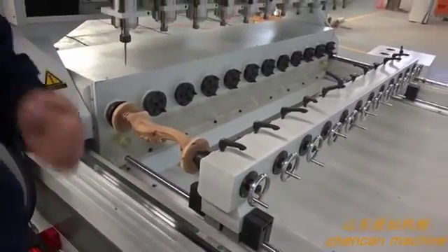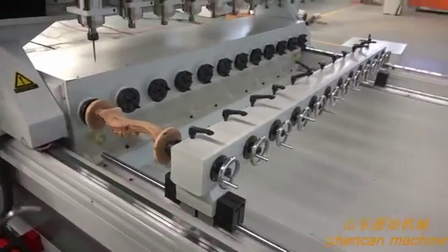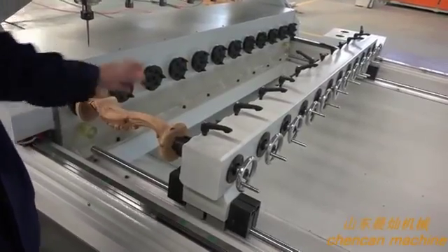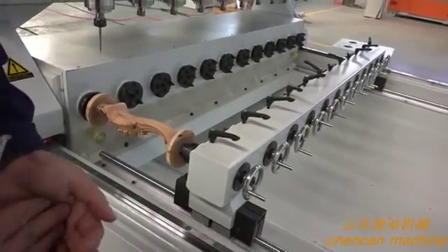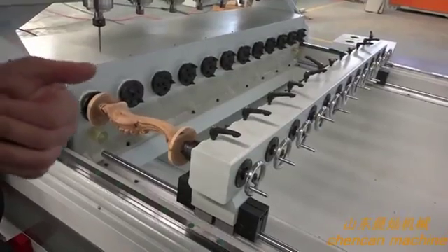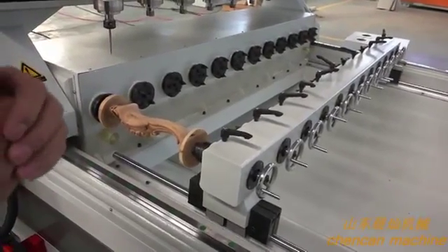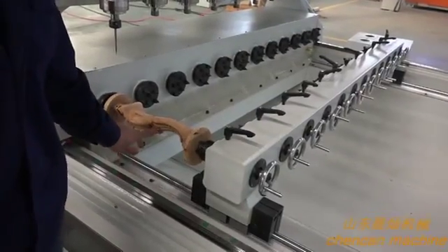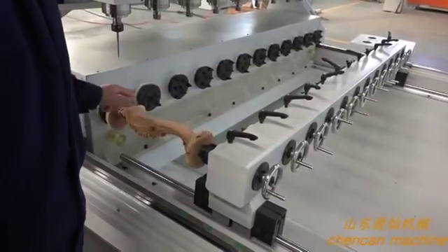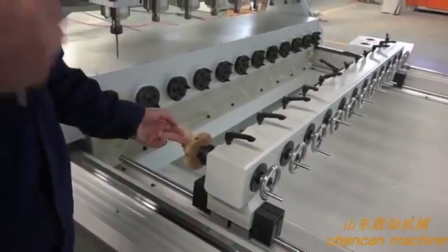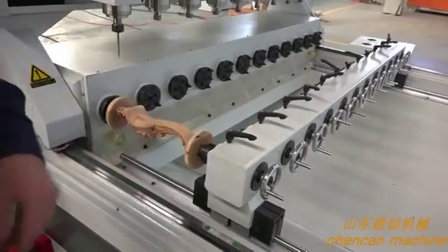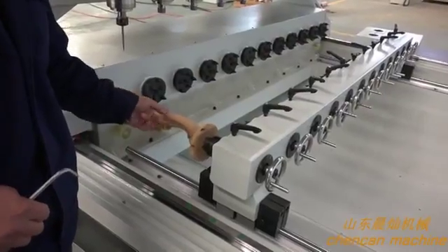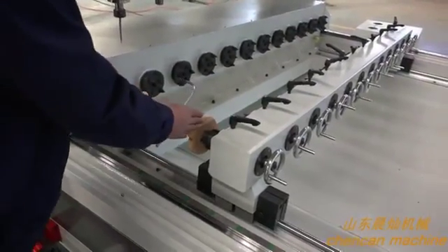Next we should set the X. Now we have already set the Y. Now we set the X. It is based on how you set up the model. You set up either in the center as the origin or on one side, based on your files. We did the files set up in the center. So we move the X to the material's center.